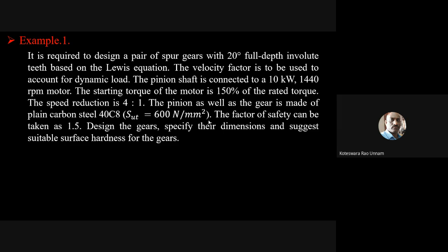type of gear transmission, open type gearing, speed reducers, or something like that, some table is given. But below that, for light and medium duty B should be less than D1, for heavy duty B should be less than or equal to 1.5 D1. So B is nothing but face width, D1 is the pinion diameter. Recommended values for psi are also given. Anyway, that we are not going to use.